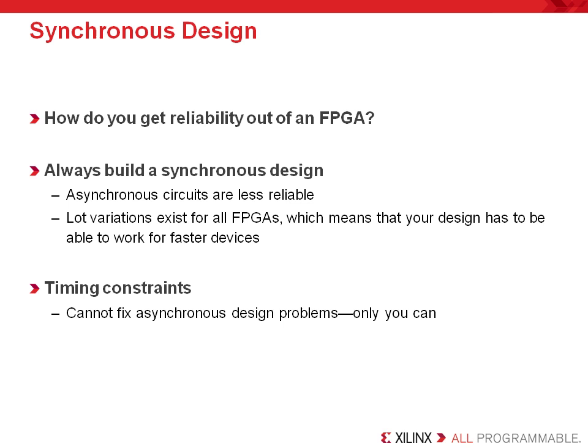How to build a reliable FPGA design is actually a simple question. The first step is to design synchronously. How this is implemented has a number of factors to be considered, but the bottom line is if you have ever had a design that had a sporadic problem, you may have been a victim of your own poor design techniques. If you design synchronously, your FPGA will operate at any frequency that meets your system timing. The key is to be aware that all FPGA makers have lot variations. This means that your part will be at least as fast as the speed grade you purchased.